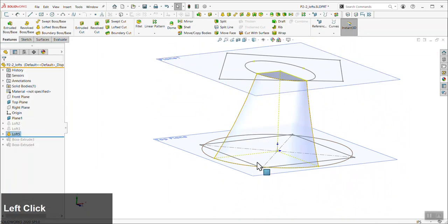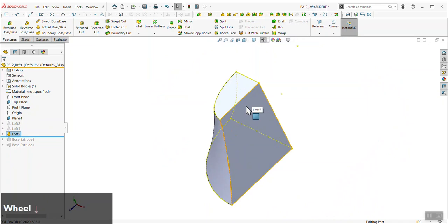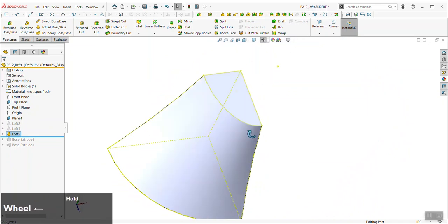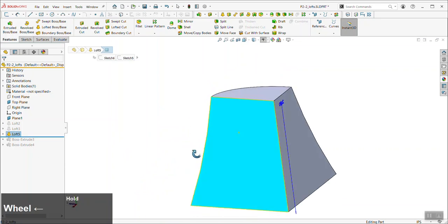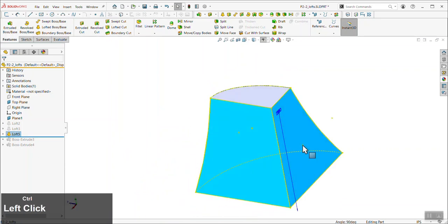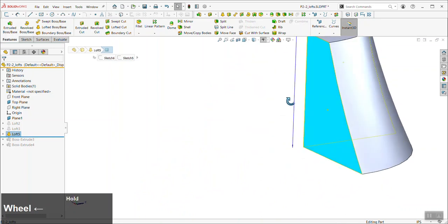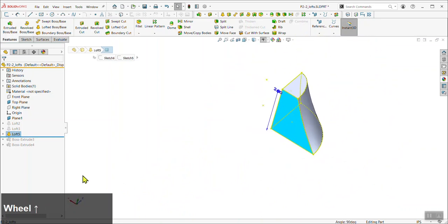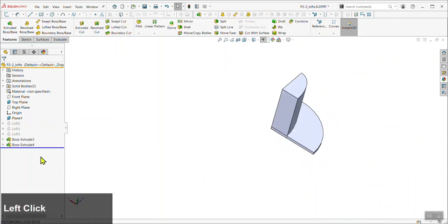Now in this case, the loft is going from this bottom shape to the top shape. If for some reason your loft fails in one direction, try to consider if it can be completed in a different direction. So could we, for example, create a sketch that looks like this blue face and loft it to this here, following these edges, so instead of top to bottom, going left to right. The knob demo that we're about to get into will explain this and illustrate this for us in more detail.